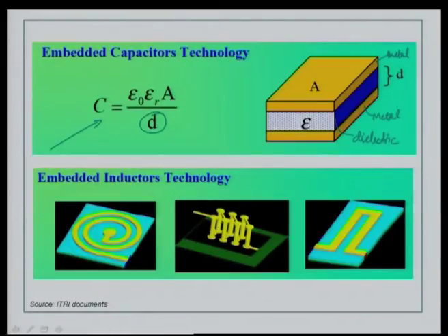So, d, the thickness, is a key component in deciding the capacitance, and then you also have the area of the conductor material, the thickness of the dielectric and the volume of the material used as the capacitor material in the sandwich structure. Based on this equation you can play around with creating different geometries that can provide different values of capacitances.